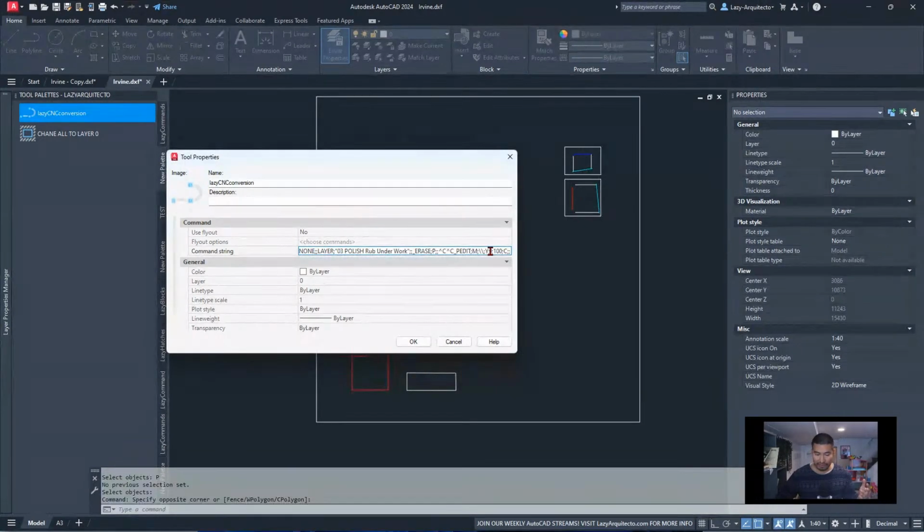So I'm gonna paste it with Control V, and of course we don't need CC at this point, right? Why? Because we are already inside this command. We already cancel any previous or active command here with this CC, so we don't need to repeat that. So let me test this.